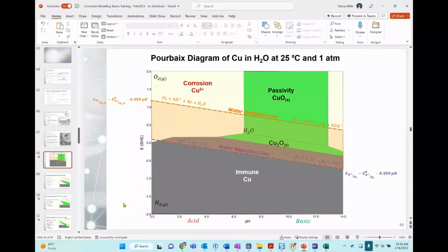There are some salts that have some chloride components, hypochlorite, I think, and you add them into the water, and that will reduce or increase the potential of the solution, and that will also have an impact on the potential of the metal. So there are different ways. It's not straightforward like the pH, but that's how you change that potential.